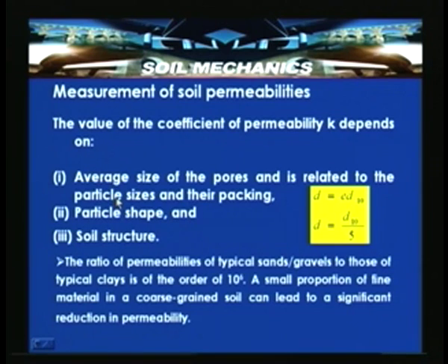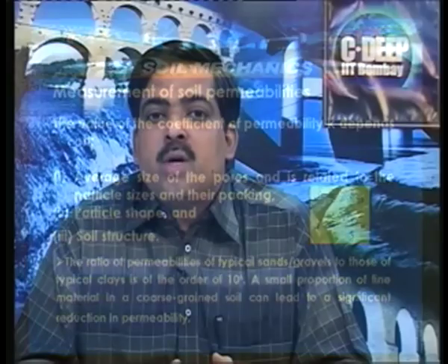We have discussed earlier that particles with a rounded arrangement can have large pore spaces. So, in those cases the permeability can be high. For example, if the particles are subrounded or angular in shape, then the flow can be affected because of the interaction of the water when it is flowing through those pore channels, passing through particles having angular shape.